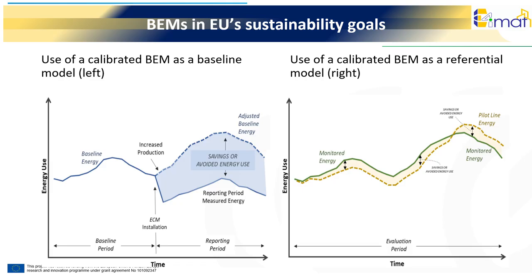accurate or calibrated representation of the building in its current or as designed state prior to any retrofit. Developing such a BEM enables the comparison of the energy performance of improvements after they have been deployed in the building. In other words, its purpose is to quantify savings or performance changes relative to the building's original or as designed conditions. And therefore, this model supports retrofit analysis, energy audits, calibration, and M&V, measurement and verification, protocols.